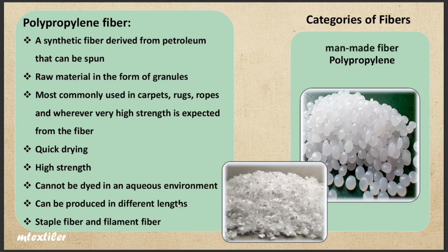In the next sections, when we examine fiber dyeing, we will understand that one method of dyeing is by mixing white granules with colored granules. This is how dyeing of polypropylene fibers is done. When the granules are melted in their production process, only at that stage can we dye them, and the colored granules are mixed according to the required color shade. The resulting filament fibers come out colored at the end of the spinning process.